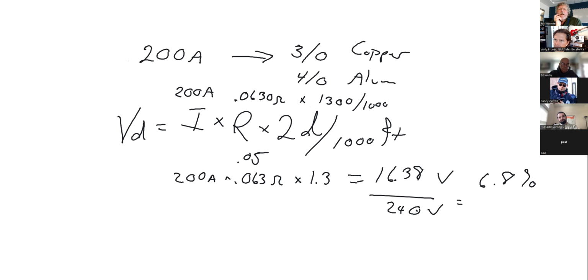Let me do a quick little internet search while I've got you on the thing. Are you putting it in conduit? Yes, he is. Yeah, no way, because that is code. Plus you don't want to. It's saying for 200 amp service, you'll need 2-aught copper wire or 4-aught aluminum. Yeah, 4-aught aluminum is just for 200 amp service.